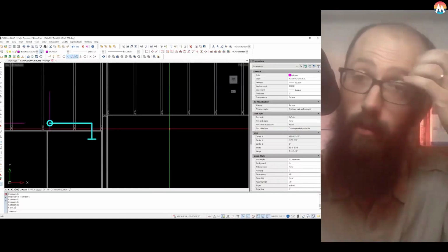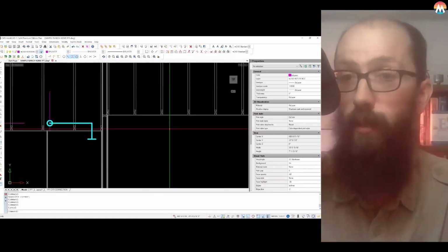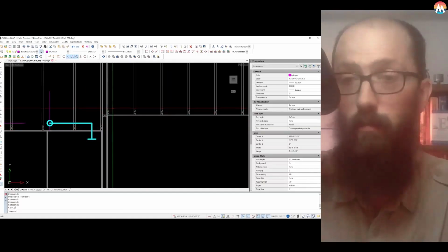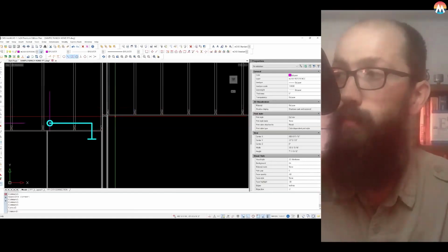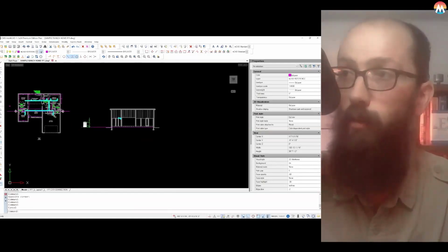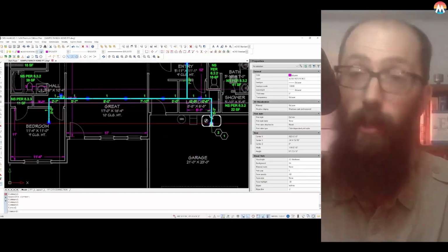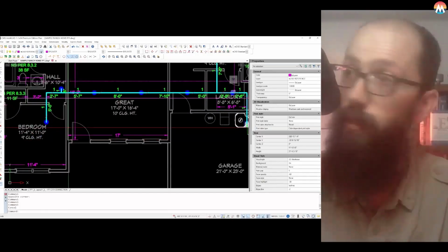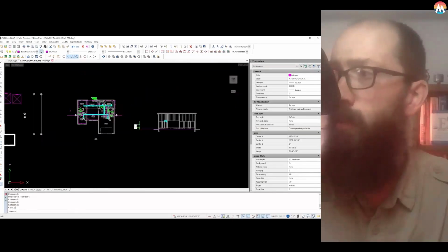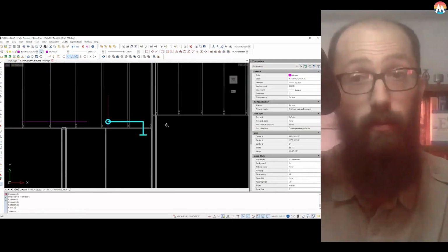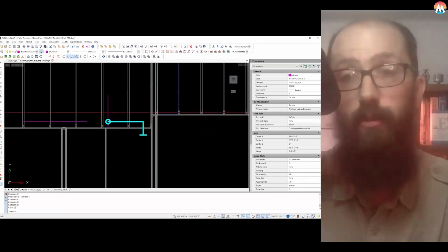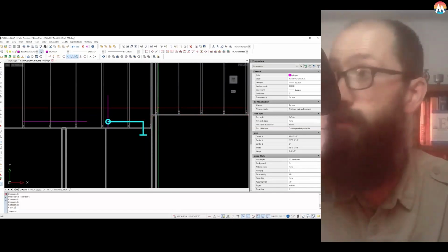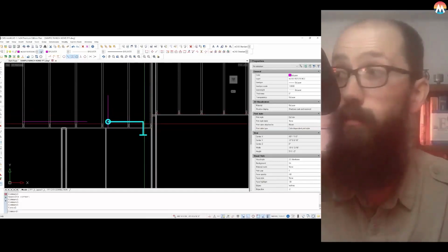And there's a few different ways we could figure out how this is going to happen. If we look at our floor plan, it happens to say right on here that this is a 9-foot ceiling and this is a 10-foot ceiling. So we need to put a 1-foot vertical rise right here. And it needs to be tight to this truss right here, or to the wall as it's going up here, so that it can be insulated.